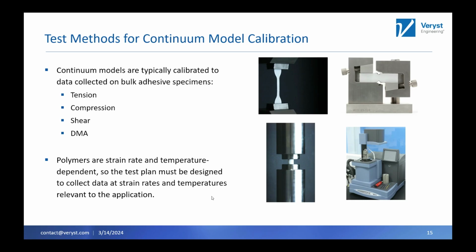So before we even start doing any testing at all, that's the first question we'll ask clients when we start projects like this: what are the expected loads? What are the expected strain rates? What's the temperature window that's relevant? Because we know we need to test the material over that range of temperatures.